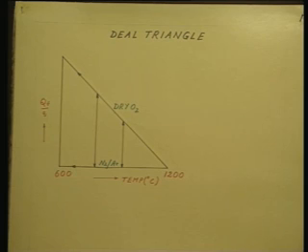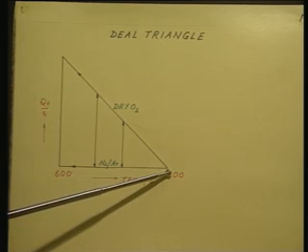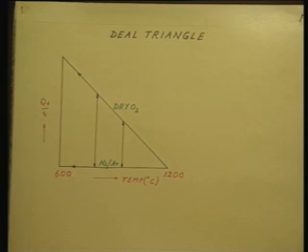What can be done in order to stop this incomplete oxidation process? Well, what is done is this: at the end of the oxidation process, that is, for the stipulated period of time you carry out the oxidation, at the end of this period close the oxygen gas flow and create an inert ambient, that is nitrogen or argon, and now reduce the temperature in this inert ambient. In this inert ambient oxidation is entirely stopped, therefore, there is no question of incomplete oxidation. Whatever oxidation took place at very high temperature, since oxidation rates were much faster, there was much less chance of having incomplete oxidation. So, then one follows this baseline and you end up with a much lower fixed oxide charge. So, this is the standard practice today.